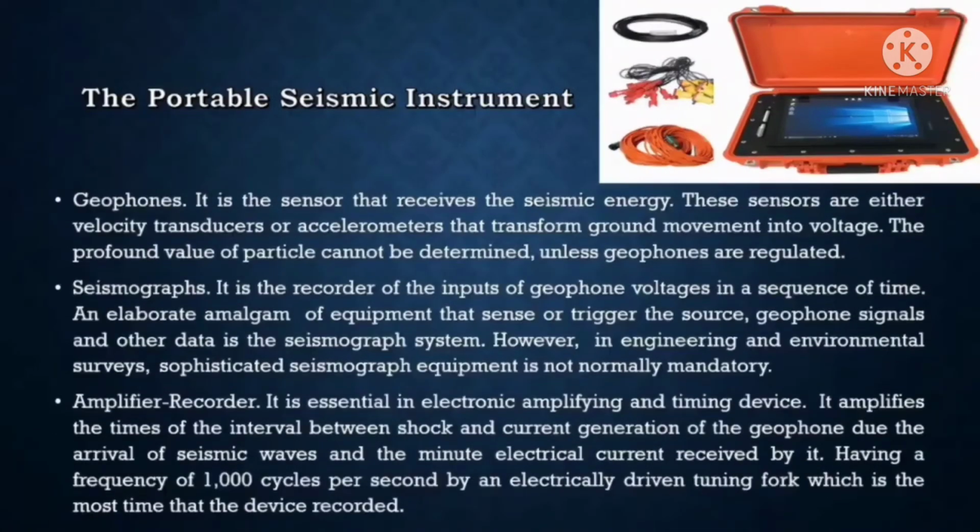The portable seismic instrument, geophones. It is the sensor that receives the seismic energy. These sensors are either velocity transducers or accelerometers that transform ground movement into voltage. The true value of particle motion cannot be determined unless geophones are calibrated.